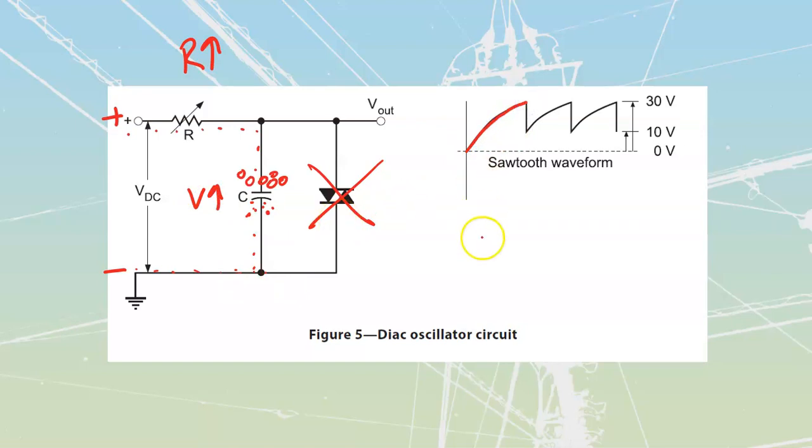And my voltage is going to slow down as it rises. You should remember that it takes 5 tau to charge a capacitor in DC. You learned that inside the second year, and that it grows along this weird sort of curve. It's called the universal exponential curve. So we see that universal exponential curve starting to grow over here.